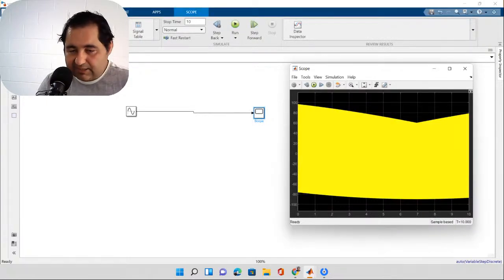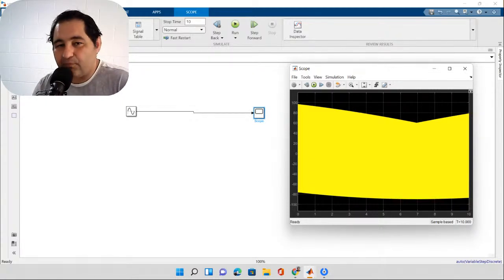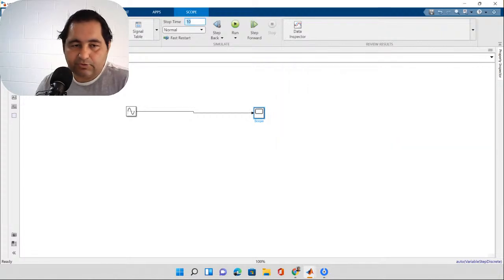And also you can see that we're getting a simulation error. In real life, that is not what is expected. So you can see the voltage is actually dropping. Why is the voltage dropping? Because the software is failing. Otherwise, the sine wave that we have is supposed to be a fixed one. So be mindful of the limitations of any software you are using. The software is not always right. All right, so go for 1 second.